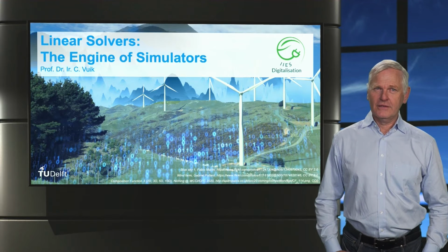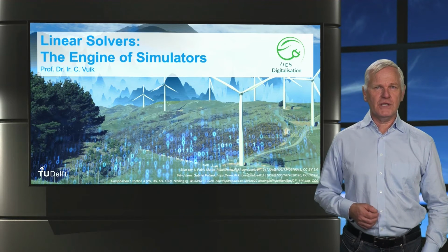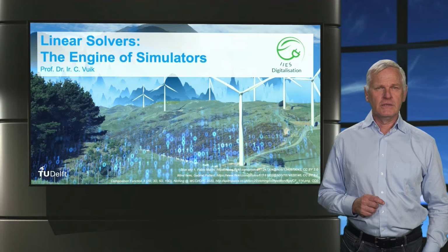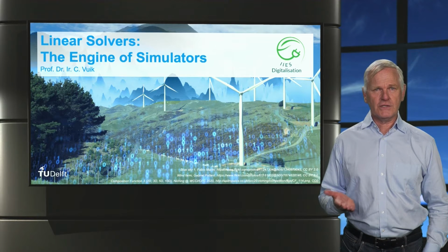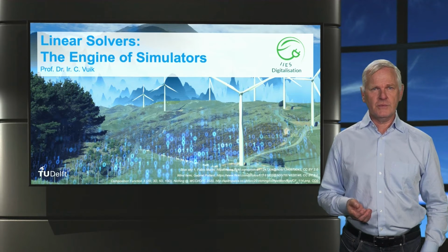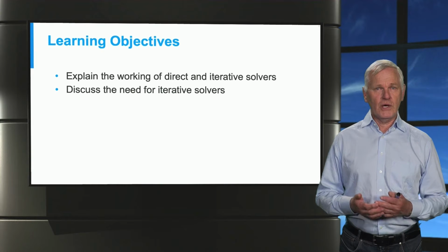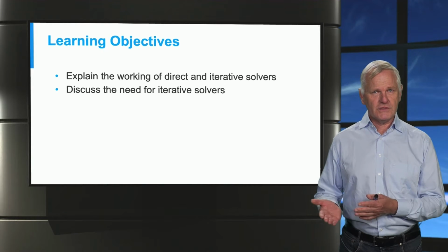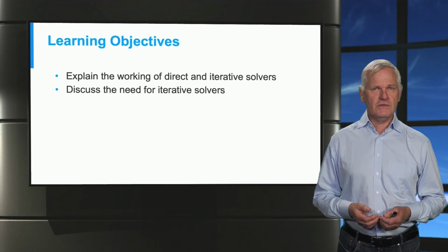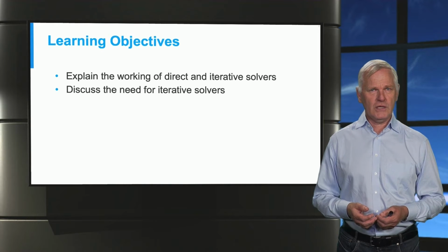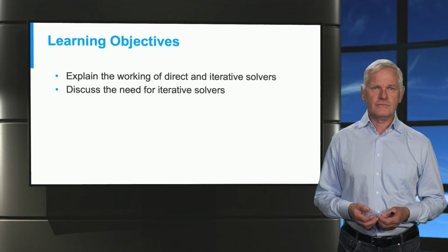Welcome back. Have you ever wondered what happens when you press Simulate on your computer? In this video we will discuss the linear solver, which is the heart of many simulators. We will explain the working of direct and iterative solvers and discuss the need for iterative solvers. But first, let's take a look at what problem we are solving.